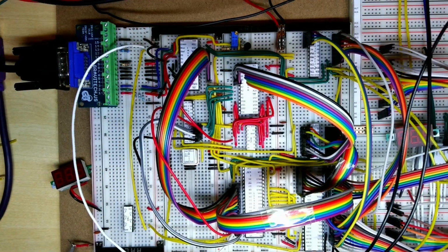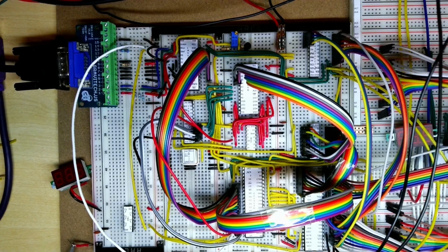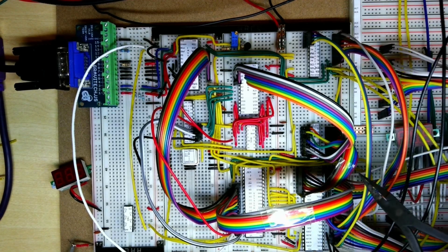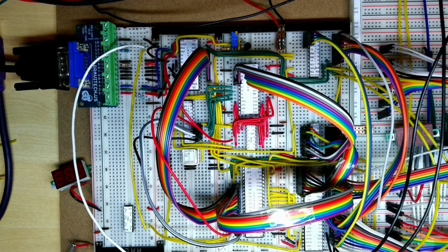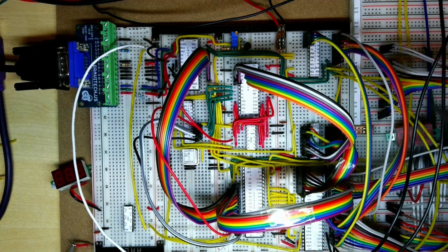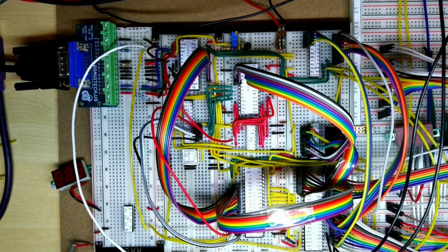Okay, so we're ready to try it now with the video RAM hooked up to the character latch and the output there. Now to start with, when we do this, we're just going to get random characters on the screen because we're not setting anything in the test program in the video RAM. So I have put in the decoupling capacitors. I'd forgotten to put decoupling capacitors in on the board, so I've actually put 0.1 microfarad decoupling capacitors close to the ground rails of most or all of the chips.